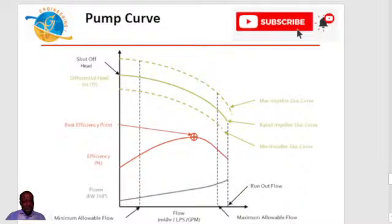Say your flow is around 50 cubic meters per hour. If you trace this up to where it touches the rated impeller diameter curve, then trace it to the vertical axis, that point will be your differential head, your total head requirement.